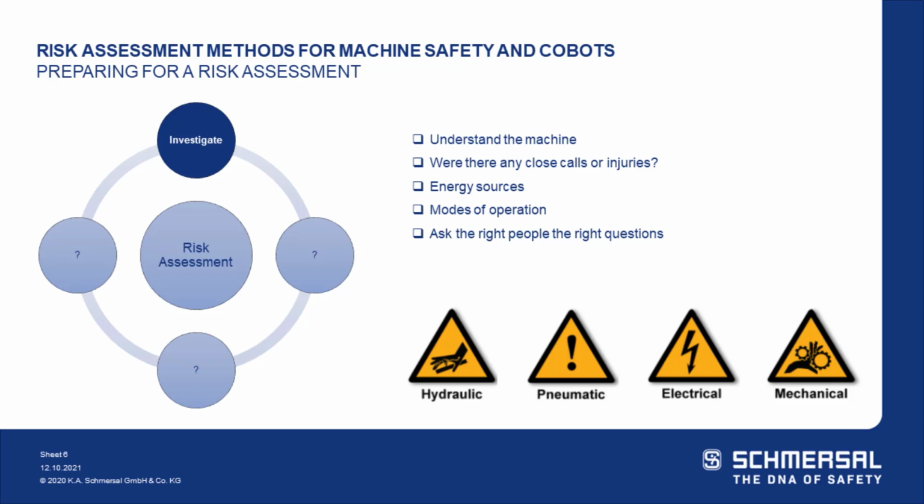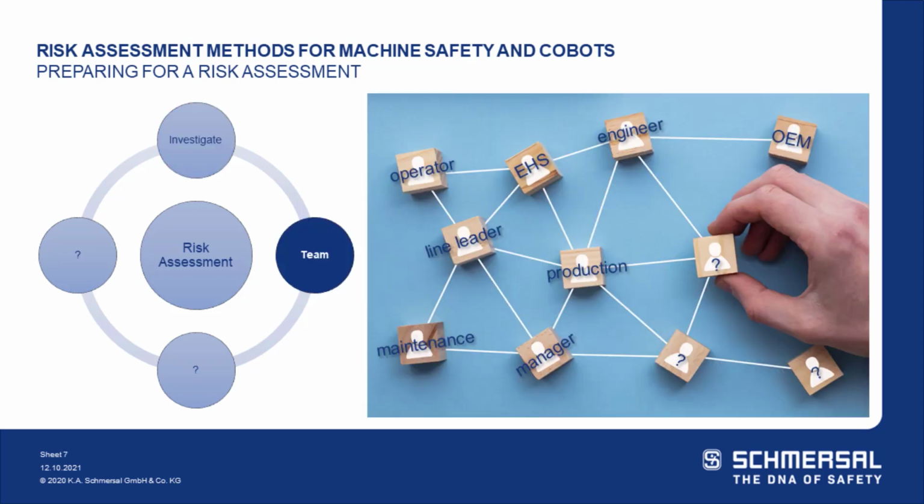And in the end, what we did was we provided a two-hand control, and the operator could jog the blades while the system was open, put them in the right position, and then close it and it can run at full speed. So we made a good solution, but if I walked away and I didn't ask those questions, they would have continued to bypass.